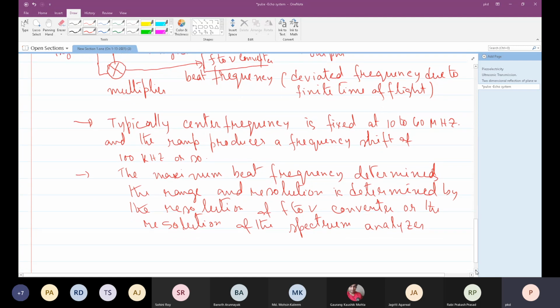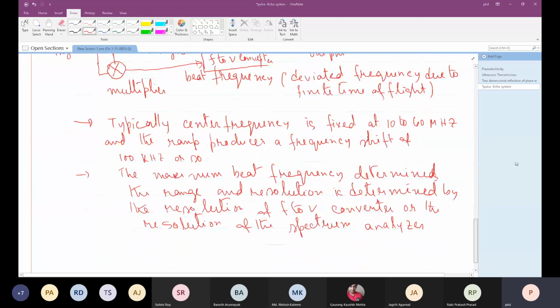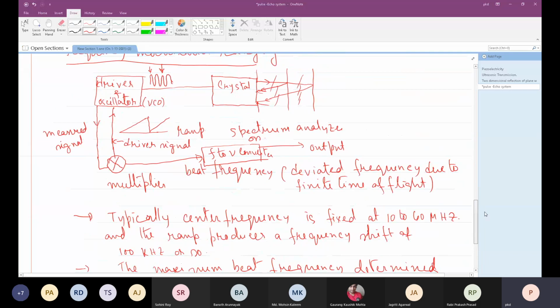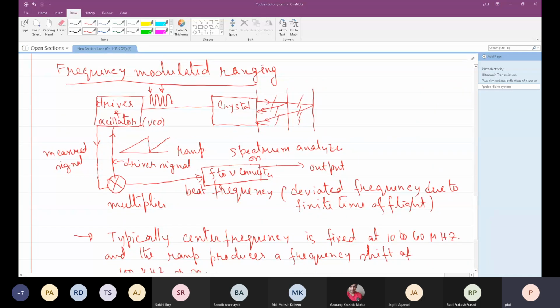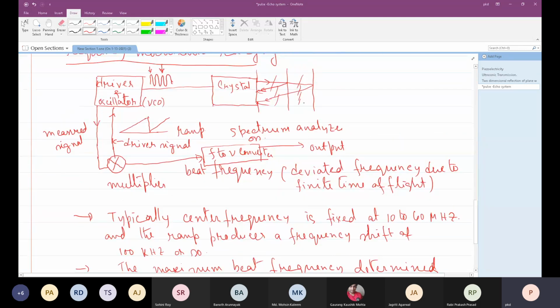Now, as we were talking about the noisy situation, in a noisy situation, using spectrum analyzer frequency measurement would be much more noise resilient than the pulse width time detection method, as in that case, invariably because of the finite beam divergence, reflection uncertainty will be there.